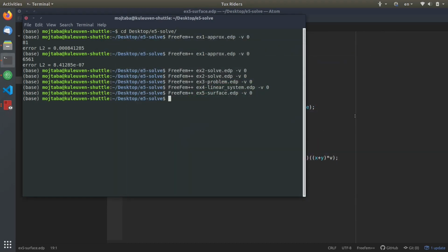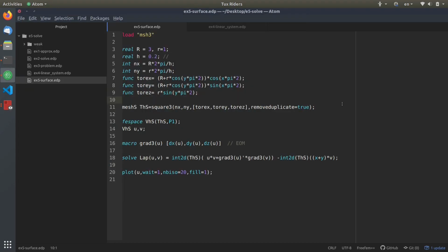Okay, so this is what we wanted to discuss in this video about various techniques to solve partial differential equations. You see various forms, all these three, in various examples of FreeFEM in the documentation and codes that people share. And it's very important to know the differences. As I said, the most important difference is actually the rearrangement that is needed in these two, and not when you want to solve it using a varf statement.